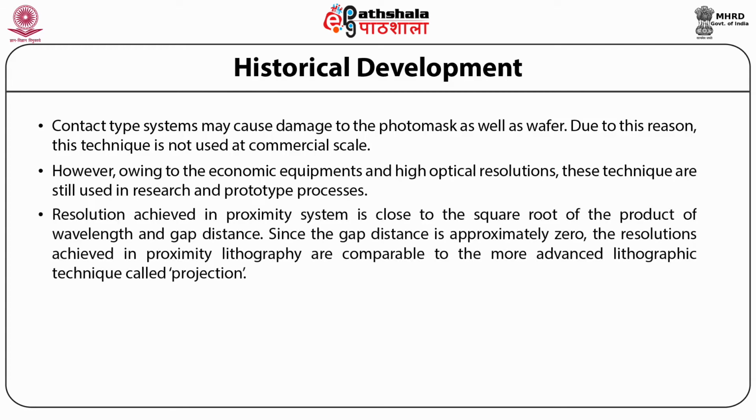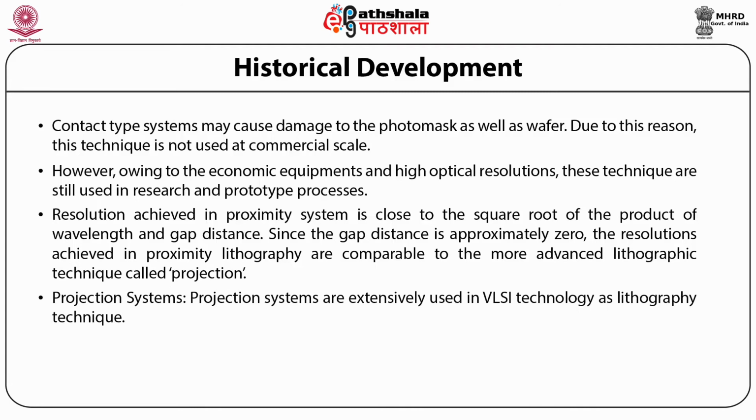Resolution achieved in a proximity system is close to the square root of the product of wavelength and gap distance. Since the gap distance is approximately zero, the resolution achieved in proximity lithography is comparable to the more advanced lithography technique called projection. Because of the low cost involved in installation of these systems, they can be used in nano imprint lithography.